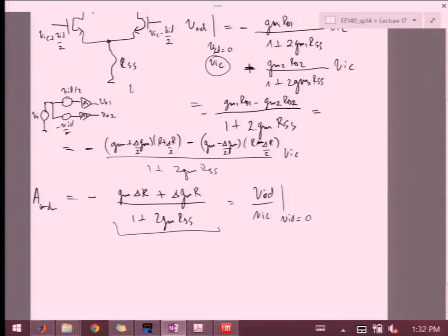And so VOD would be VO1 minus VO2, and VOC would be VO1 plus VO2 over 2. That was our half circuit approximation. So we're still assuming you can cut in half circuit because the perturbation is small, but then the difference in the gains would cause all these problems, right? That's an approximation because normally, with slight perturbations, you can't actually cut the circuit exactly in half because the two halves are not exactly the same, right?